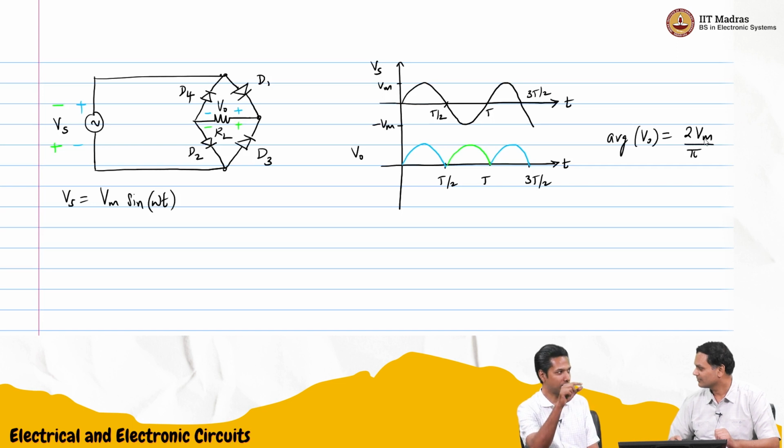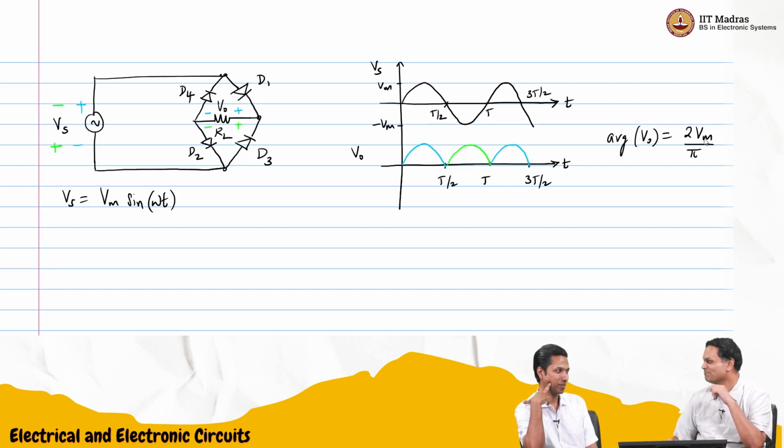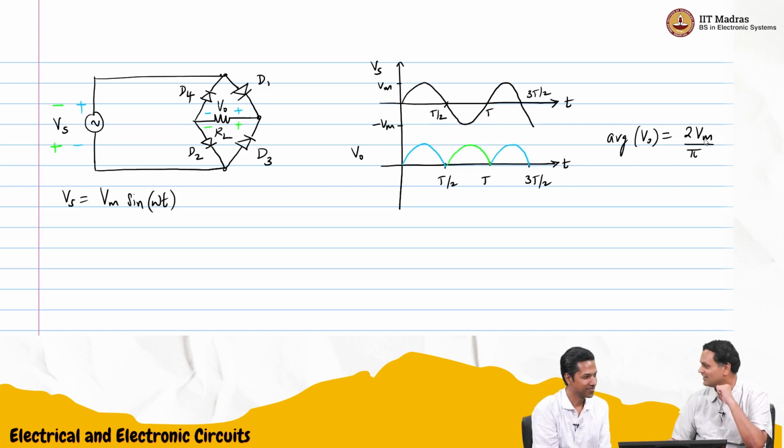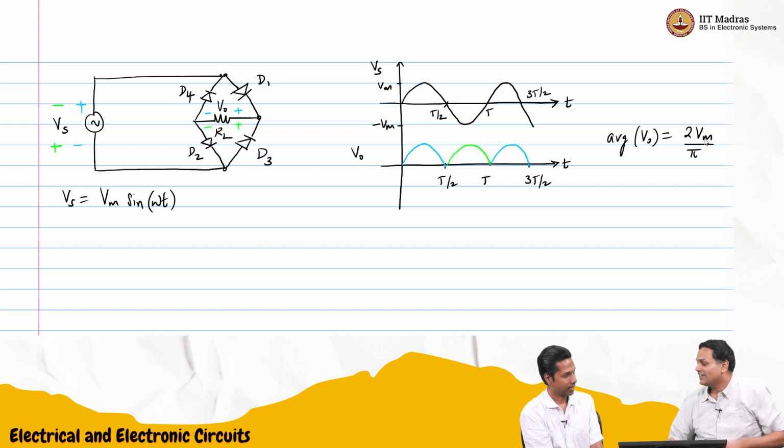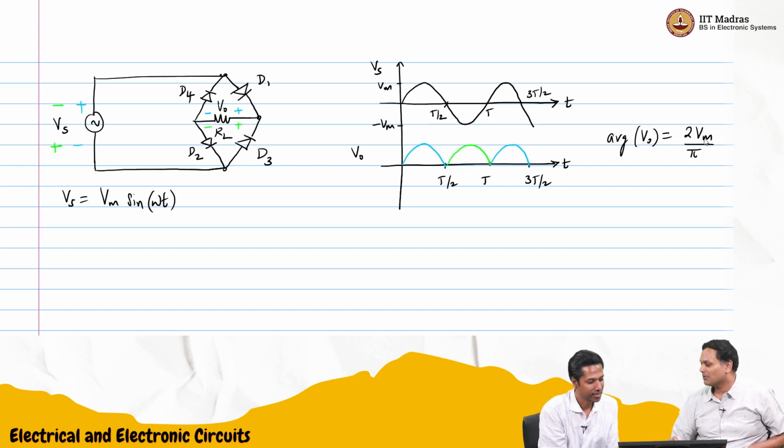Maybe only small differences from the half wave. When you use a practical diode, approximately 0.7 was getting dropped on the positive side. Now that will become 2 times 0.7, because there are 2 diodes in series. In a practical sense, if the voltage is large enough, then it is not a problem. But if it is too small, it's a problem.